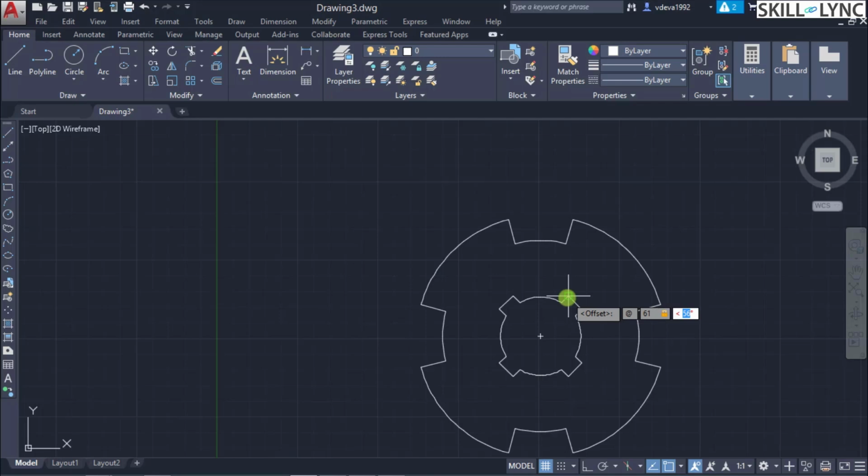As you can see, this hole from the center axis here is offset by 30 degrees. So again, the angle is going to be measured from this, so it's going to be 60 degrees from this point. So you have got this center point located. Next is the diameter. The diameter of this hole is 12 mm. Now it's got positioned here.